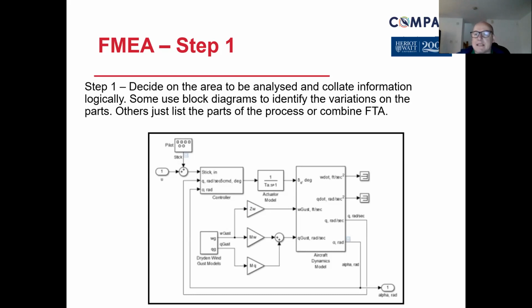As a result of that, put in place the backup plan. And if you use a fault tree analysis, which works hand in hand with this, you've got your AND gates and your OR gates, so look at the series or parallel approach, and then decide, maybe we need to design more into it to avoid that particular situation.